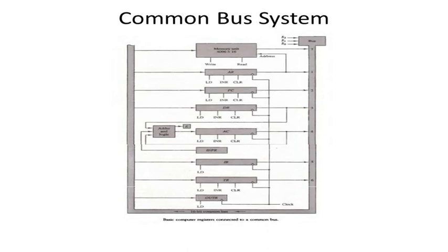And here is the accumulator. When you give an input like 0, 1, 1, immediately the accumulator will be selected. The accumulator works just like a processor. Here also there are 3 inputs: load, clear, and increment. This is connected with an adder logic circuit. The accumulator is added with another register, and the result is also stored in the accumulator. If any carry is generated while adding, that carry will be loaded into E.